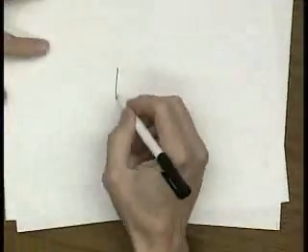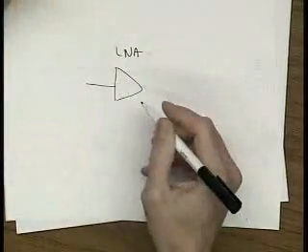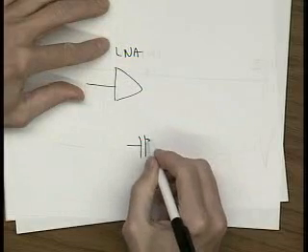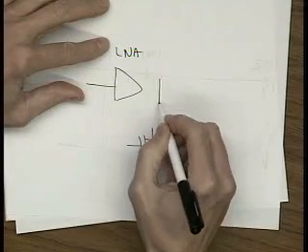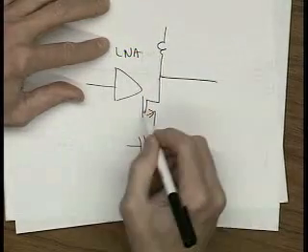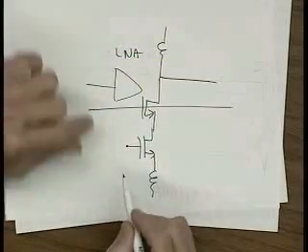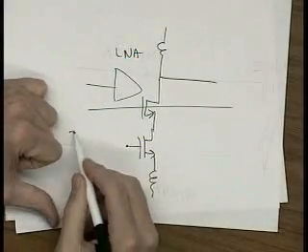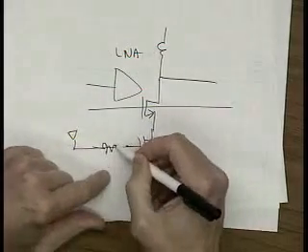So what are the tough design problems? There are these first gain stages, these low noise amplifiers. You've got to worry about these noise sources, not only of resistors. Let me just finish this up. Let's say it's a cascode, and we have a tuned load. Let's say this is your basic amplifier, and this is hooked to your antenna, right? Maybe there's an inductor here to tune out the capacitance.